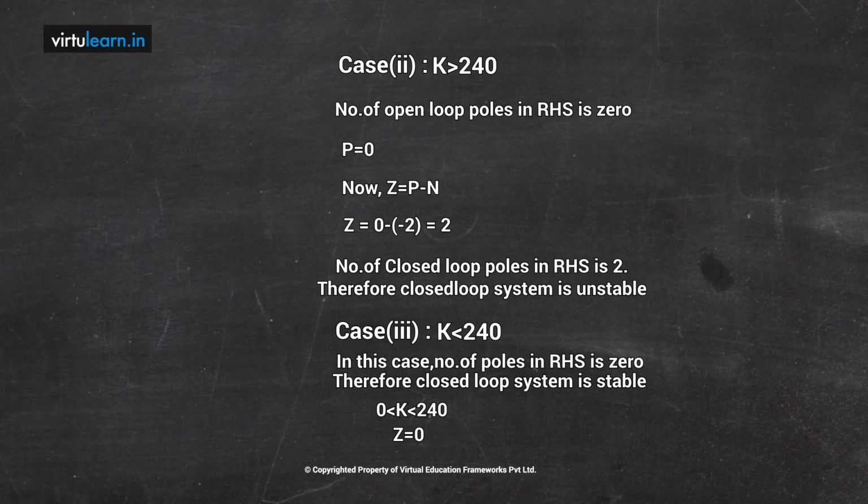When you draw the line here and look at the inner circle direction, it is going to be clockwise at that particular point. Similarly, for the outer one, we again have a clockwise direction. Both are clockwise, so I can say n is equal to -2. If encirclements are anti-clockwise, n is positive. If encirclements are clockwise, n is negative. Therefore, in this case, two encirclements in clockwise, n is equal to -2.